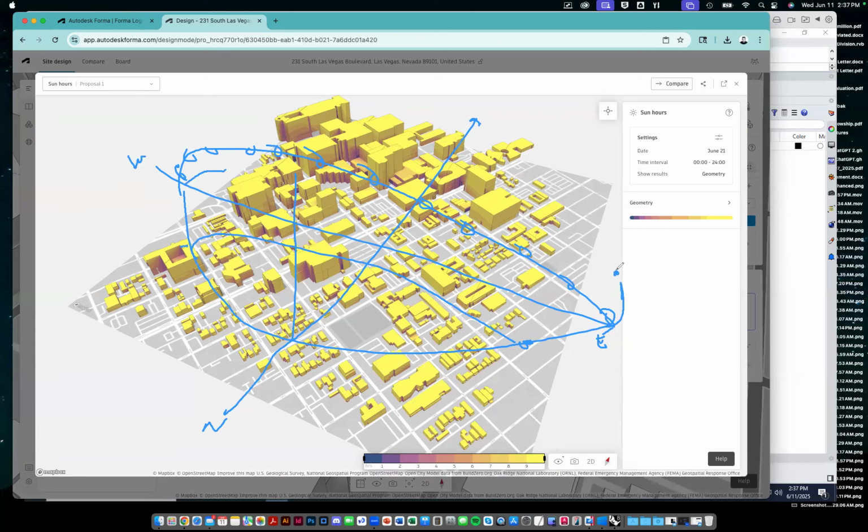And so that's why in June, the north faces aren't necessarily always shaded, right? Because you get that northwest light towards the sunset, you get that northeast light when the sun rises, and it's really high in the sky. So doing overhangs to shade outside can get really tricky, right? Like, the shadows get shorter. They're longer in the winter and shorter in the summertime, as the sun is much higher in the sky.